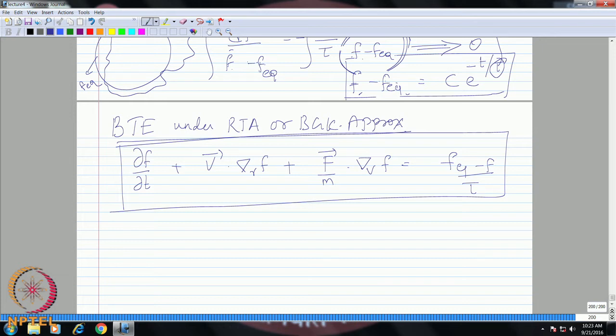And what is so important about this Boltzmann transport equation? Now, if you want to non-dimensionalize this, let us consider a case without any external force. So, let us for the time being ignore the third term. You can choose some reference velocity u reference for the sake of non-dimensionalization, and therefore, you can substitute this reference velocity into the actual dimensional velocity. Similarly, you can choose a reference length scale.